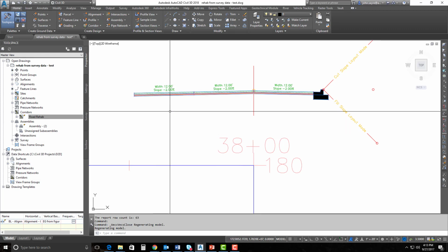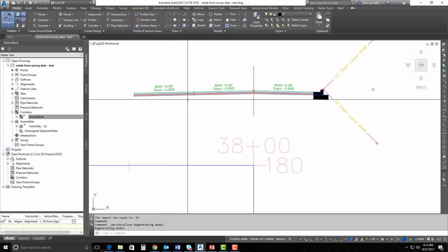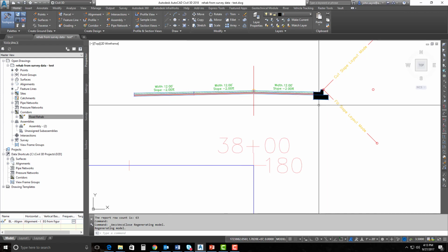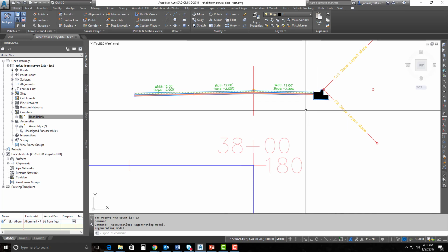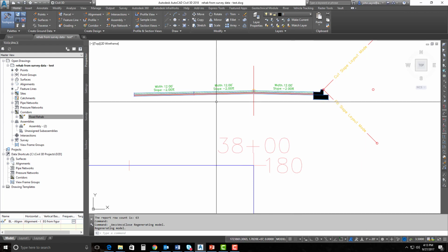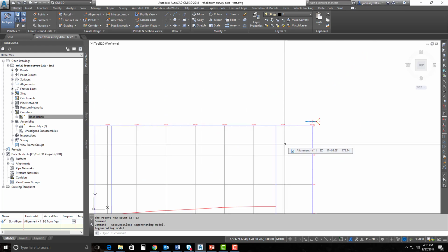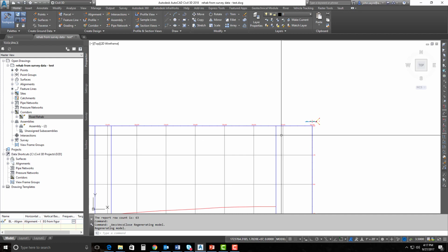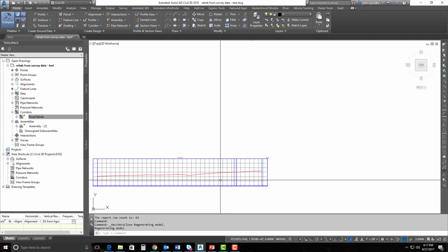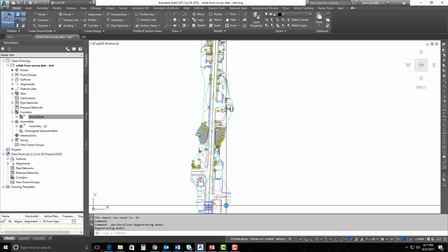Just got to remember to target it correctly, and we can continue to add individual pieces and parts as sub-assemblies, like curb and daylighting tools, to this automatically generated assembly. So as you can see, the interactive cross-section based workflows for milling, leveling, overlay, and the reporting that it gives us is a nice new feature inside of Civil 3D 2018.1.